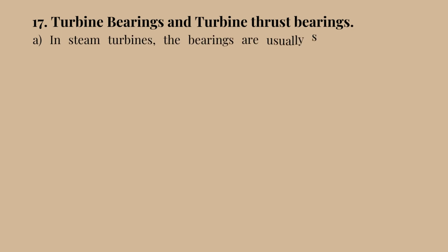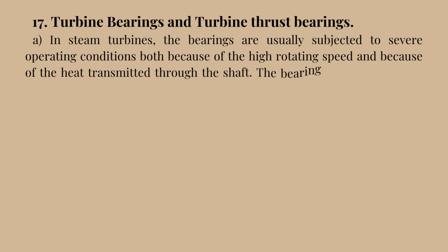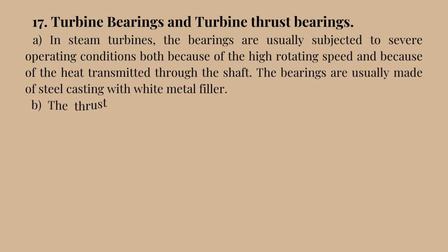17. Turbine bearings and turbine thrust bearings. A. In steam turbines, the bearings are usually subjected to severe operating conditions both because of the high rotating speed and because of the heat transmitted through the shaft. The bearings are usually made of steel casting with white metal filler.